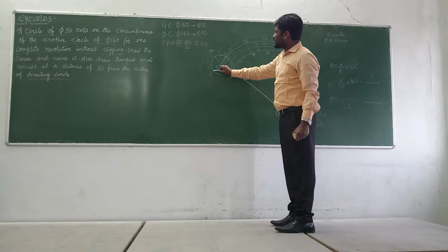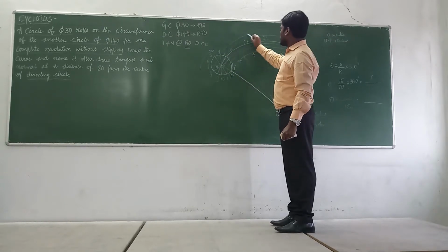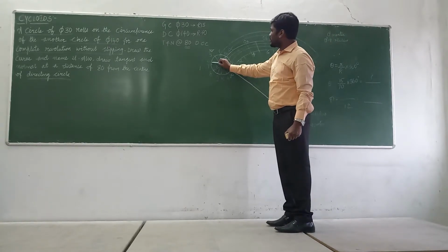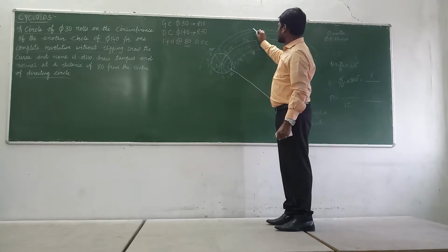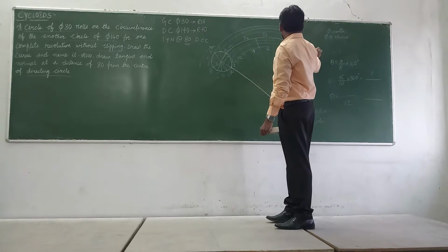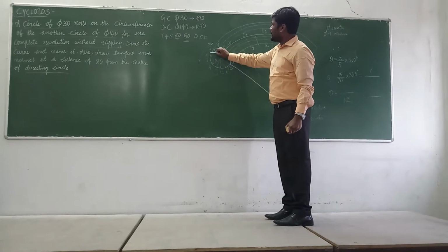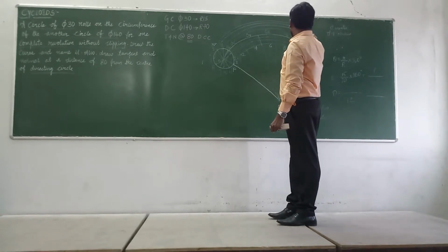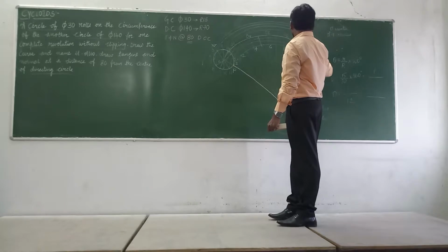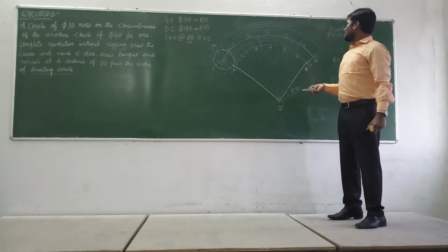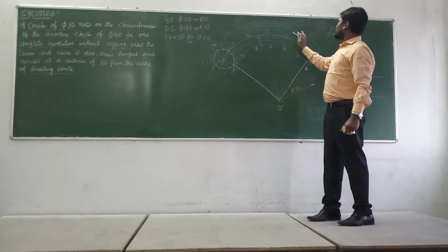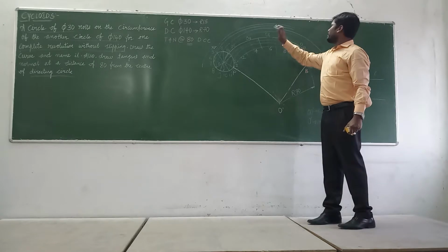Next, O dash 8 is the radius, then draw an arc. These are all thin lines of general construction. Next, O dash 7 is the radius, O dash as the center, draw an arc. Finally, O dash 6 is the radius, O dash as the center, draw an arc. So you will get the whole set of arcs or curves which we trace from the circle for our general construction method.